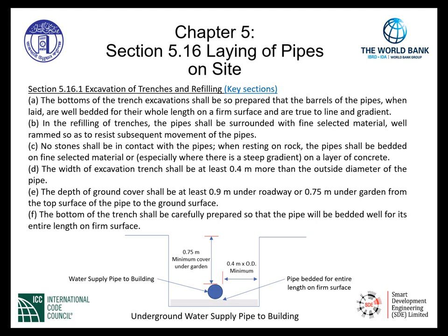Item C, no stone shall be in contact with the pipes. When resting on rock, the pipe shall be bedded on fine selected material, or especially where there is a steep gradient, on a layer of concrete. So again, bedding is important here. We do not want any bowing of the pipe, deflection of the pipe that may cause damage to the pipe or fittings themselves and cause leaks and failure.